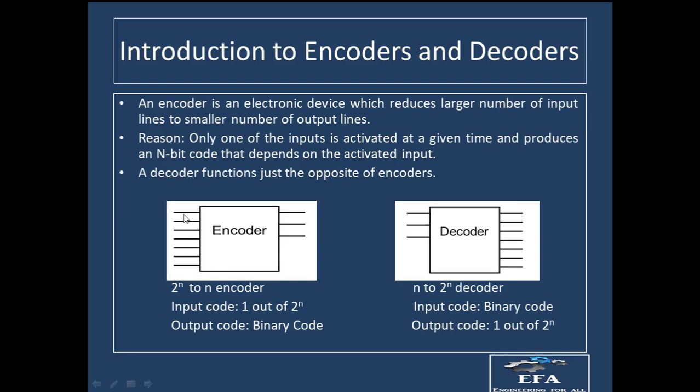Let us say we have x number of input lines, and out of these, only one line is carrying information, and the rest are vacant. This information will be in the form of bits. When this information is received from one of the input lines, the number of output lines is selected according to the number of bits, and all these input bits are distributed onto those output lines,